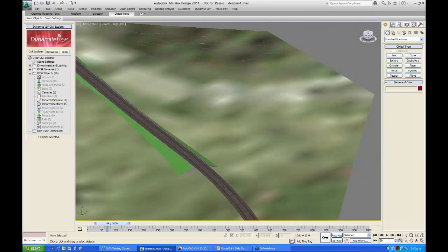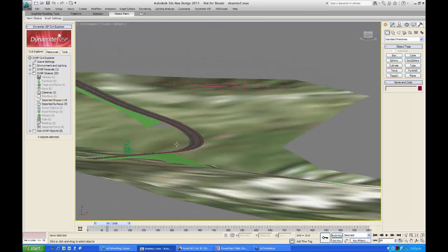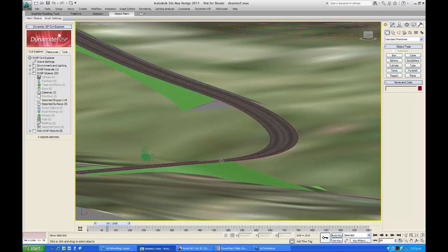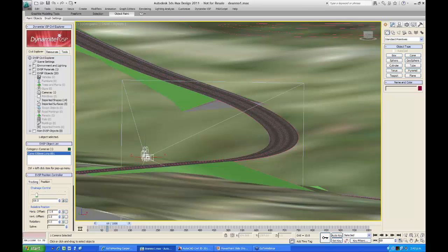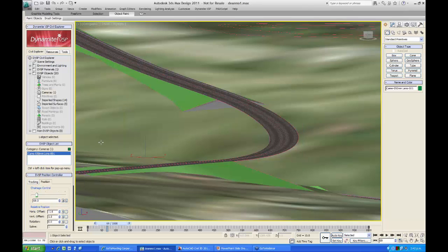All right, so we then look at the other components of 3ds Max. Now, we'd like to make this bridge here for a start. We can just get the camera out of the way for a moment. If I pick on the camera, it highlights and appears over here on the left, and I can tell it to hide the selected object, and that's what we need to do.